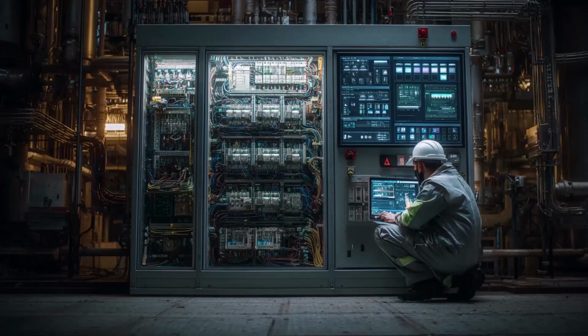Any of our Windows-based assets that aren't being used as OT assets, like an HMI running Windows, yeah, we should be patching those once a month. We need to be patching those data historians. We need to be patching those engineering workstations. We need to be patching those Active Directory domain controllers in OT. There's a lot to think about.